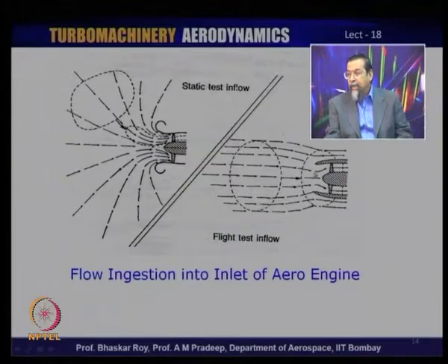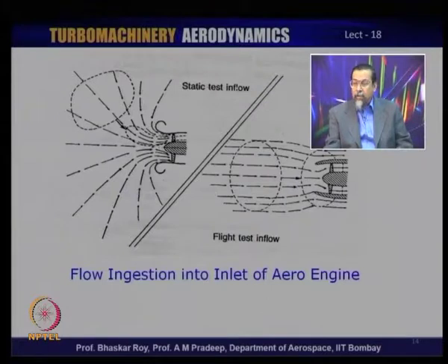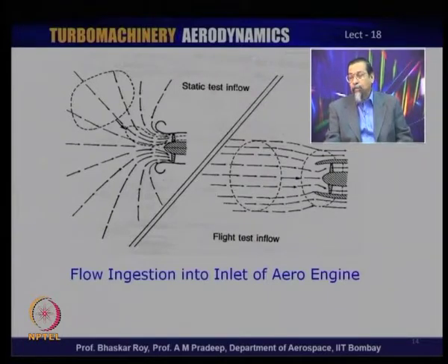So, as we can see here, the noise coming out is in waves. It will propagate in waves like this, whereas in a situation like this, it will propagate in waves in all directions. So, in a takeoff condition, the noise very quickly spreads in all directions, whereas in flying condition, it normally spreads straight in front of the compressor or fan of an aero engine. So, it depends on what the operation of the engine is as to how the noise actually propagates from the source of noise creation.